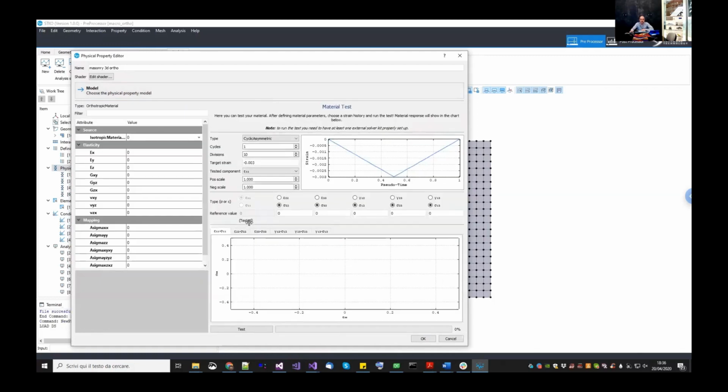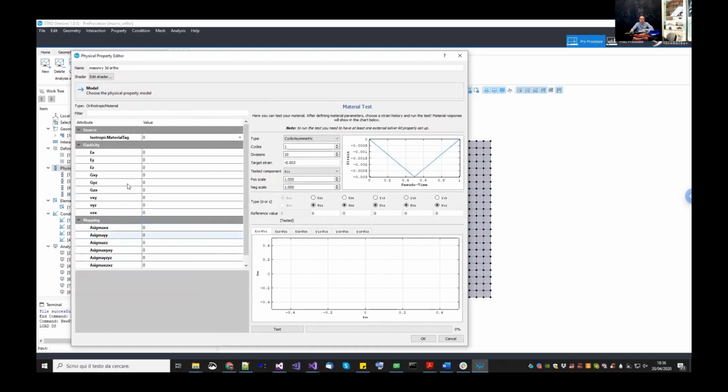It is a mapper, so like the plane stress or the plane strain, but of course here you have some parameters. So the first one is the 3D isotropic material that you want to convert, and it is the Masonry isotropic 3D. Then here you need the elastic modulus, or every elastic constant, so elastic modulus, shear modulus, and Poisson ratios for the orthotropic elasticity of the Masonry. So you need to compute from your tests all the elastic constants to construct the orthotropic material, okay?